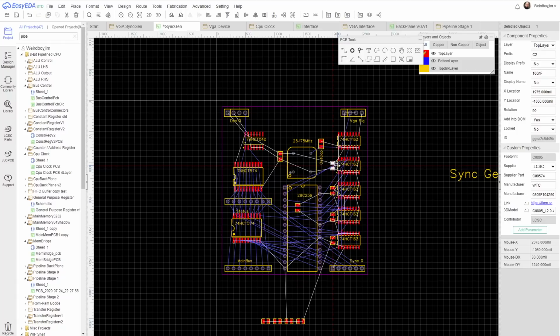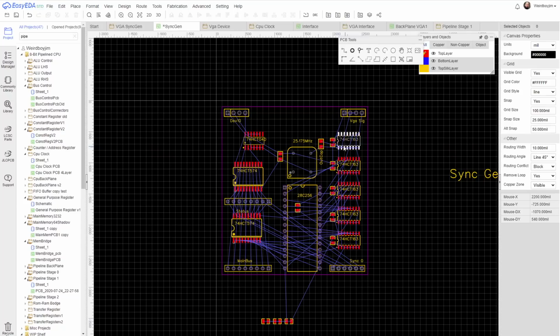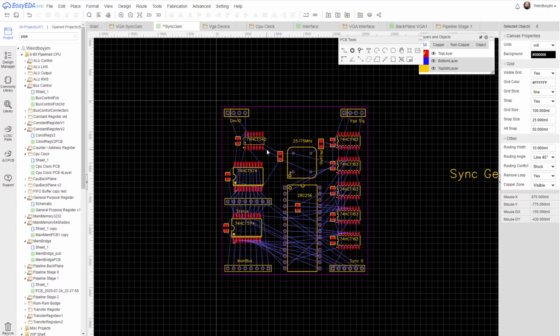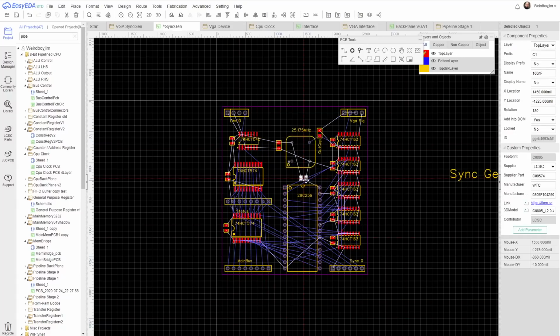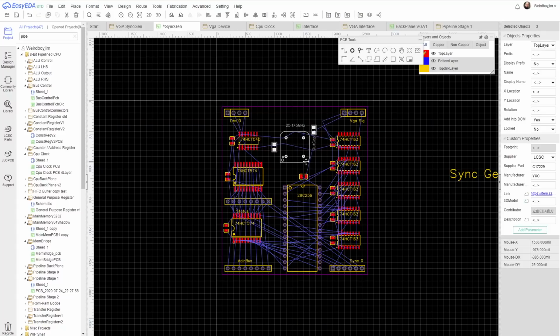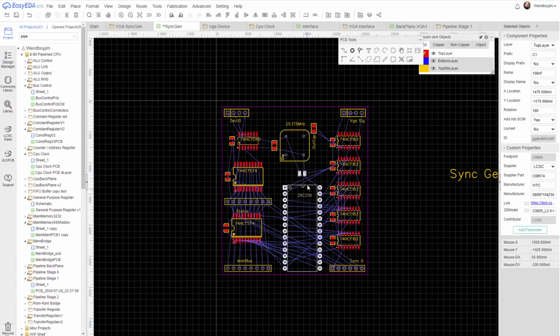One thing I will say about this circuit is these HCT163s, one of these needs to run at 25 megahertz, and that is right at the boundary of what the HCTs can do. So I am considering switching just for some of the counters to a different logic type. I think probably ACT, just to give a bit more clearance. I will use a socket for this, I think.